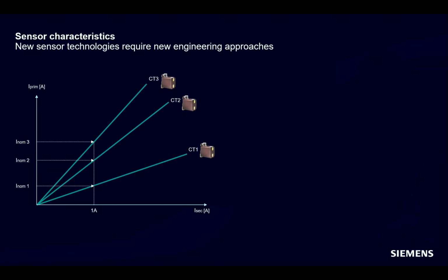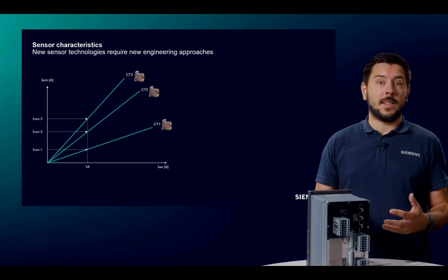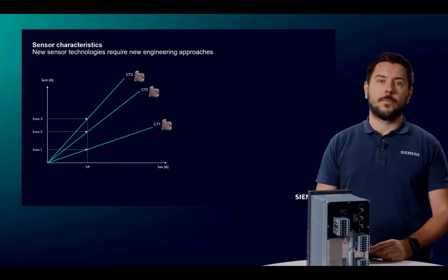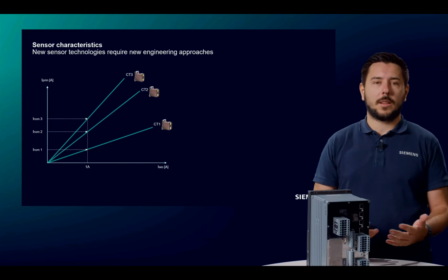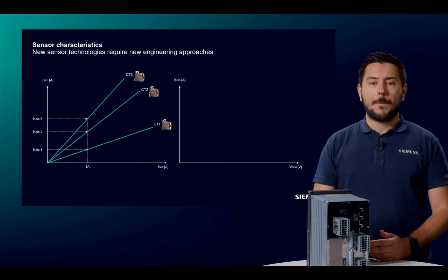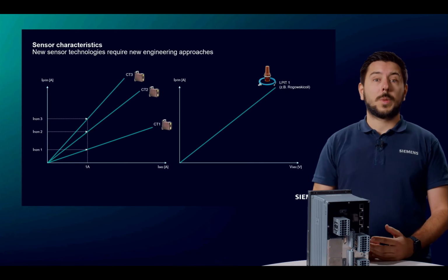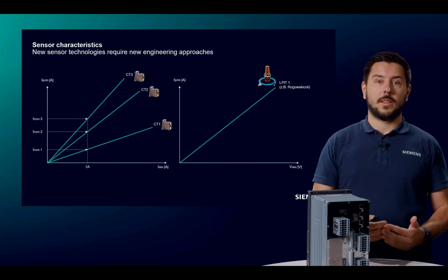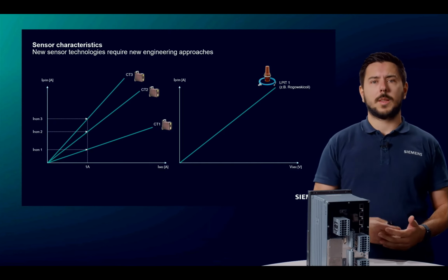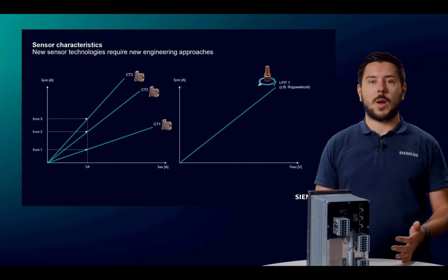This standardization has made it possible for protection devices to be connected to basically any current transformer and always operate in the same measuring range. If a higher current was to be measured, the transformer was selected accordingly. The major advantage of the sensor technology should be the wide working range and the associated lower variance in transformation ratios. This means that a Rogowski coil can be used for a wide range of nominal primary currents.